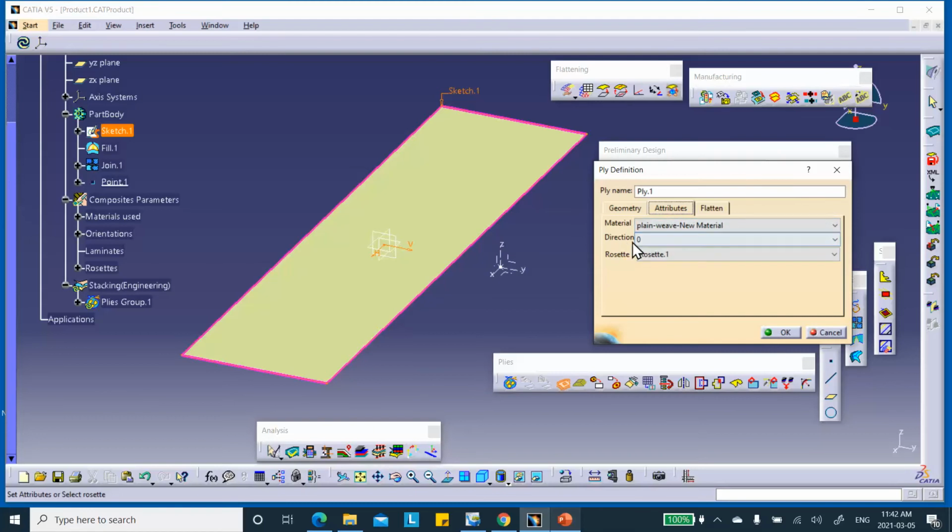And what that means is that this first ply that I'm creating, actually this is the one, because of the way I did the draping direction being up. Remember I changed the draping direction so it's up. So this is going to be the bottom one. The first ply is going to start from the bottom, okay? So it's going to be 45, okay? And that's pretty much it.